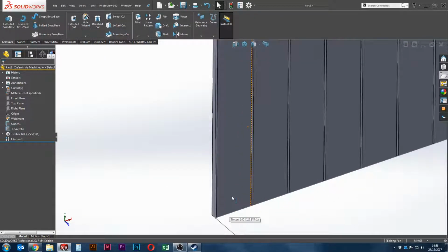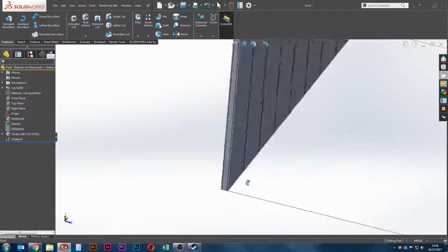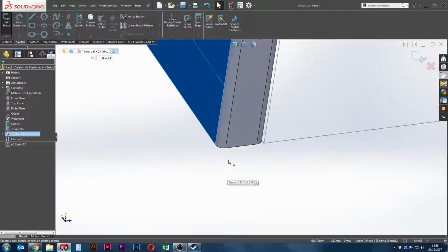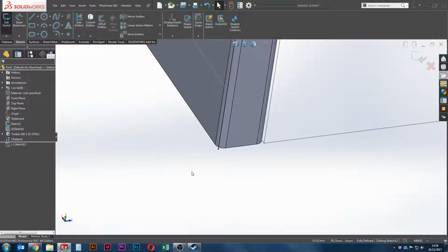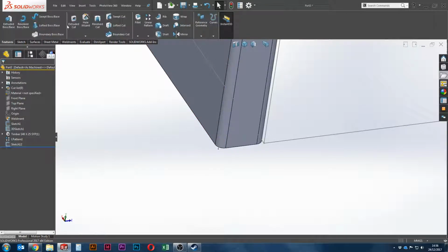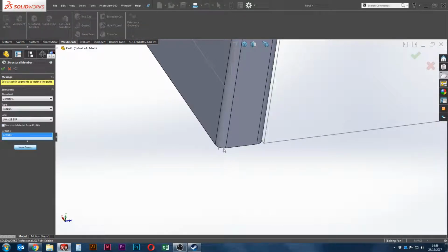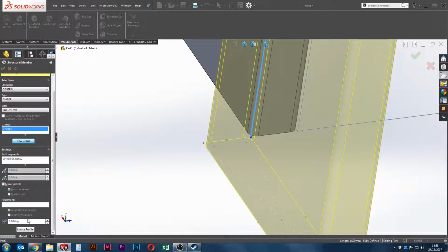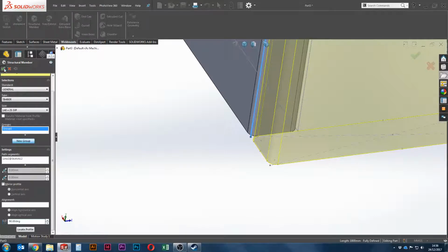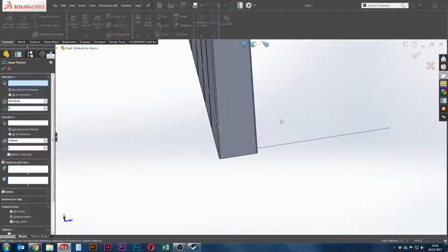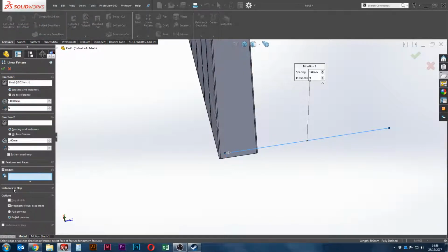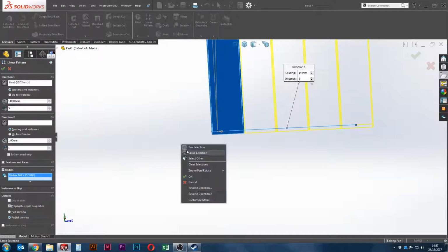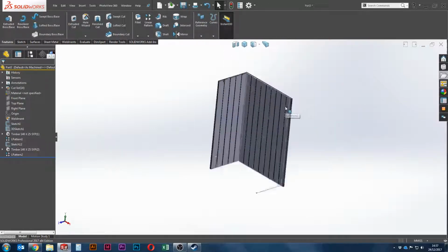And then I'm going to create, on this face here, I'm going to select this line, convert that so that we've got this point here, exit that, Weldments, structural member, same timber profile again, select that, then again locate profile, click that point, and then I'm going to spin it 90 degrees, so it's there like so, and then feature, linear pattern, bodies, this one, and I'm going to do this one 5. Okay, so we've got kind of an overview there.